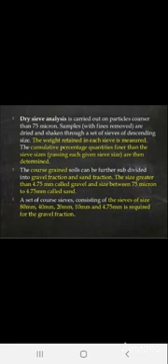The coarse-grained soil can be further subdivided into gravel fraction and sand fraction. The size greater than 4.75 mm is called gravel, and the size between 75 micron and 4.75 mm is called sand, right? So a set of coarse sieves consists of the sieve sizes 80 mm, 40 mm, 20 mm, 10 mm, and 4.75 mm. Just remember these; they are required for the gravel fraction. What is gravel? The size greater than 4.75 mm, right? So that number of sieves is required to sieve the gravels.